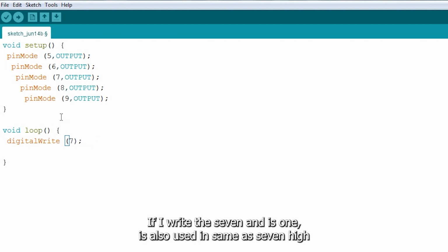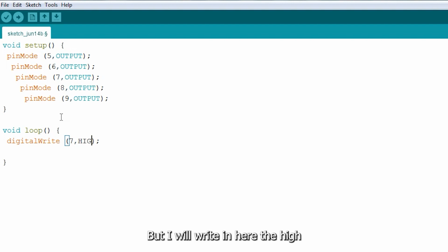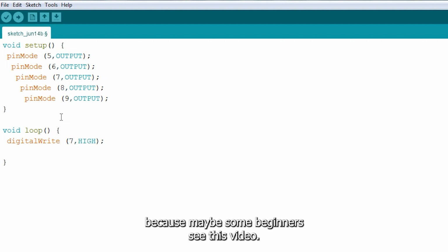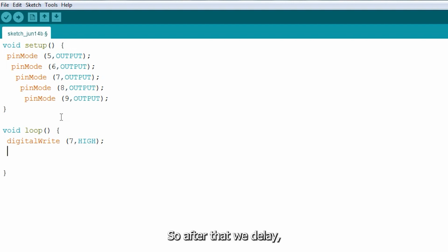If I write 7, 1, it is the same as 7 HIGH, but I write HIGH here because maybe some beginners see this video. After that we write a delay, for example 200 milliseconds.